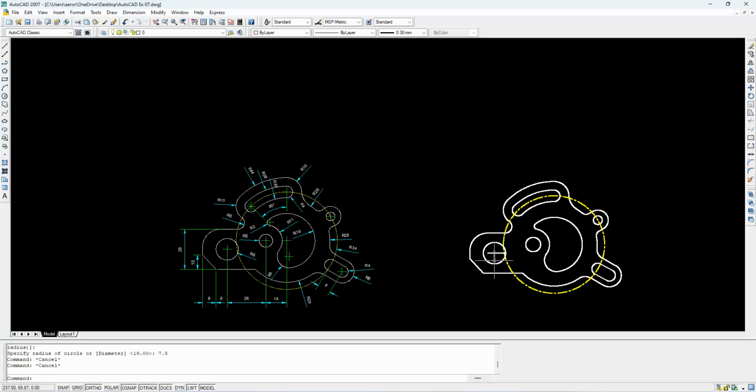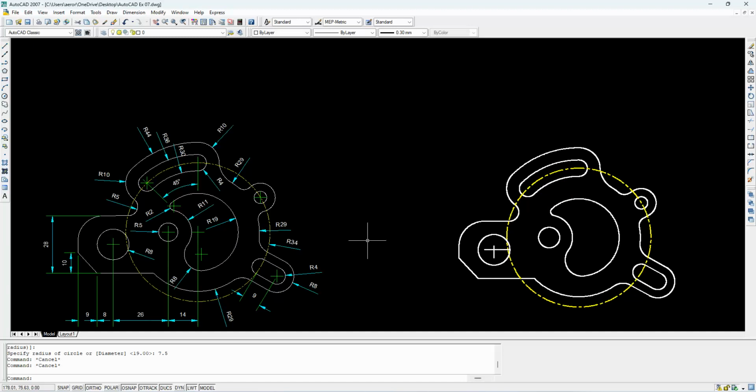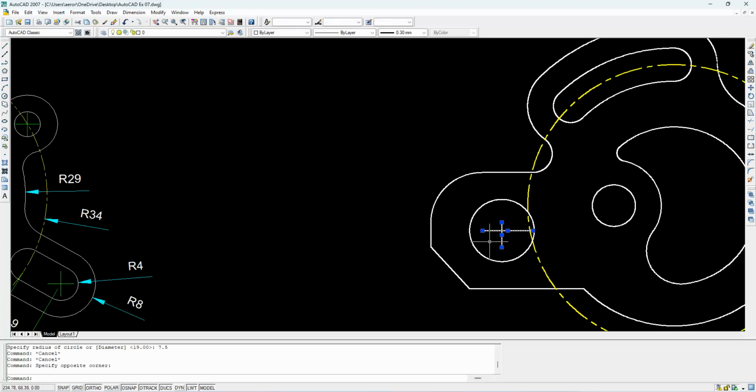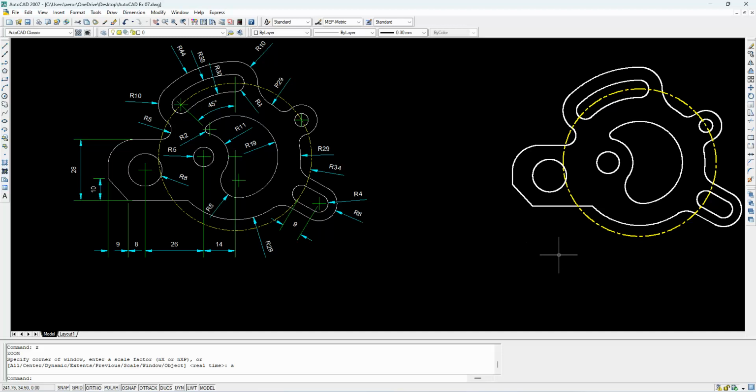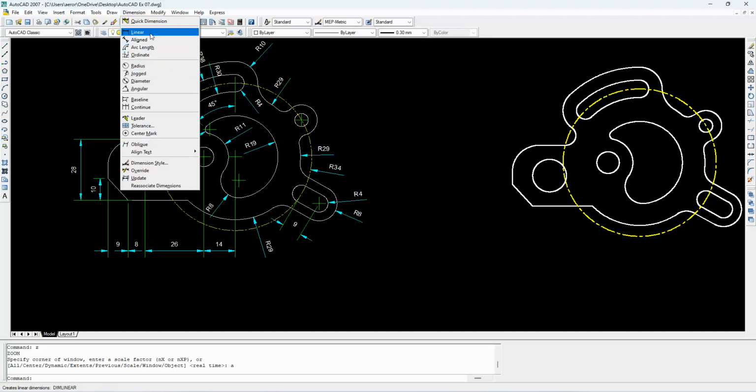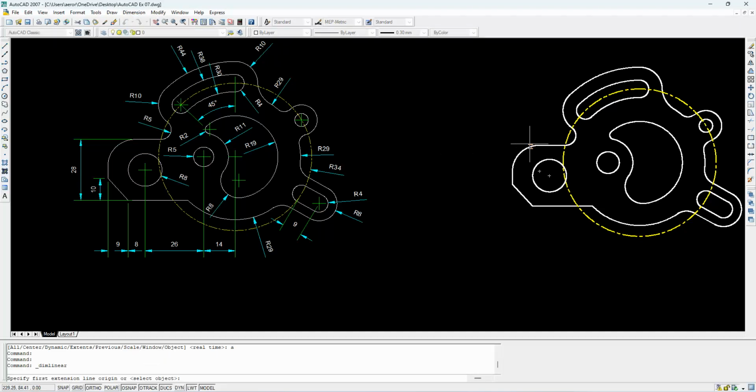Now the drawing is partly completed. After dimensioning, the drawing looks good. So now you can delete the reference line. So nearly the drawing is completed now. Now you can go for dimensions. Dimension, you can go for linear and select this point, the vertical point. So it comes as 28. Similarly from this point to the vertical point, so this comes 10.